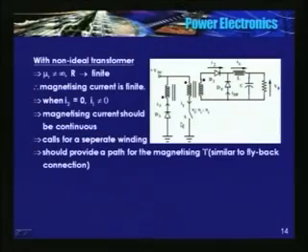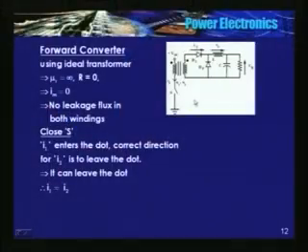So see, this is a non-ideal forward converter using a non-ideal transformer, or a practical forward converter. Mind you, the previous forward converter cannot exist. You cannot have a forward converter with a 2-winding transformer. This cannot exist, because the source has to supply some ampere turns to establish the flux in the core, and